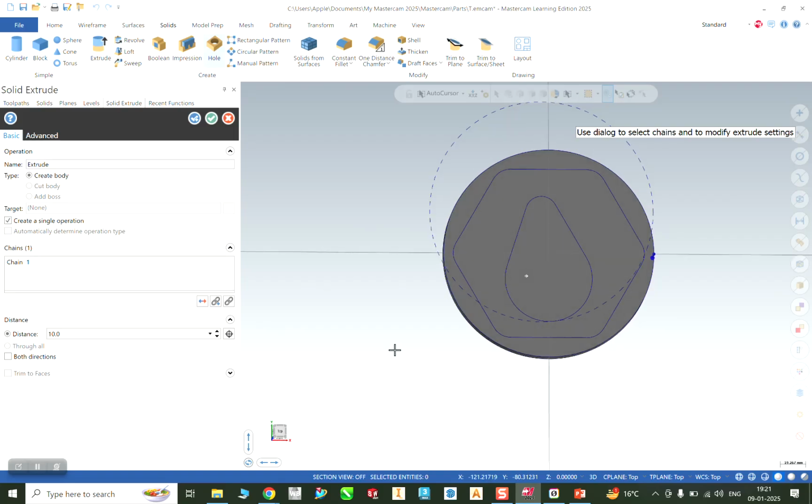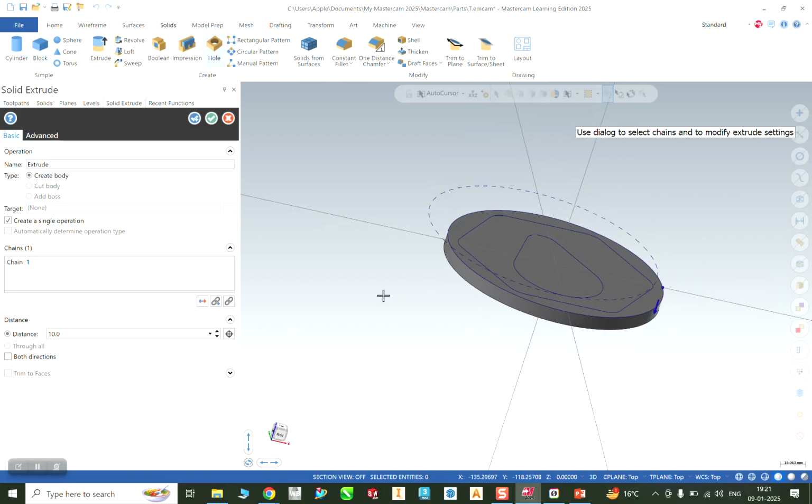Automatically you will see here at height it has taken. So it is at lower direction, so we need 20 mm. Just click 20 mm. And if you want to change the direction, no? There is basically your reverse all option. You can bring it over here. Okay, you need to bring it lower side so that your other geometries are visible.